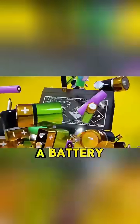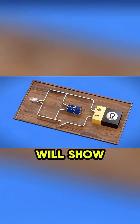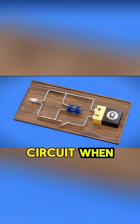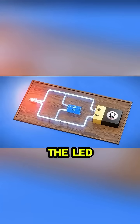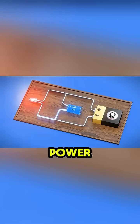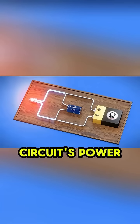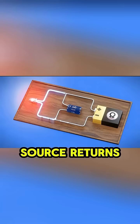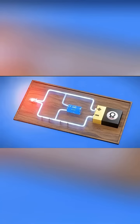You might think it's just like a battery, but their functions are quite different. This practical application will show you. In this parallel circuit, when the power is on, current flows to both the capacitor and the LED, charging the capacitor. When the battery suddenly stops providing power, the capacitor's stored energy discharges, briefly maintaining the circuit's power. When the power source returns, the capacitor begins to charge again, waiting for the next chance to discharge.